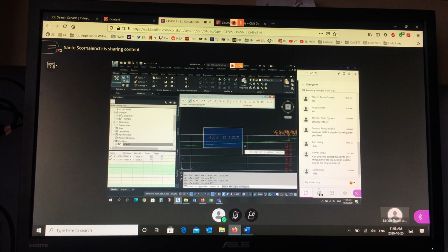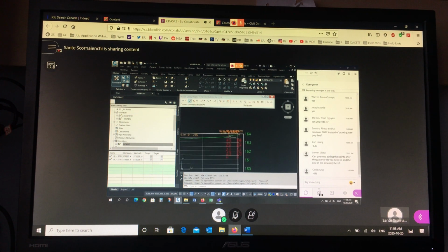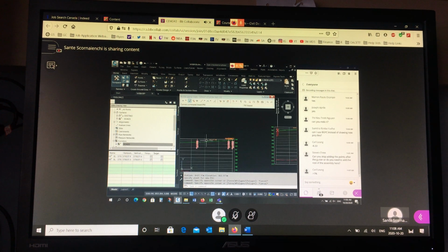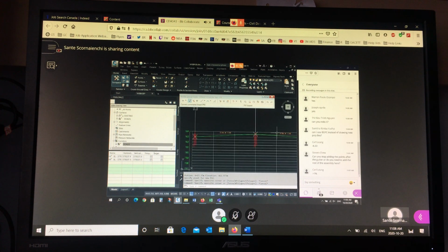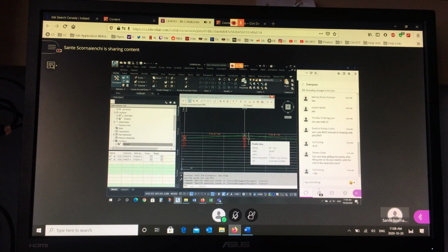We calculated something a little less, we rounded it up, so the gutter is going to be a little steeper than the 1%. So we started with 1%, we calculated what this slope should be, we rounded it up, which means the slope from the gutter all the way around both sides to the entrance of the gutter should be a little bit steeper than 1%. So again, this is not a surprise. It's confirmation that you did your work correctly before.